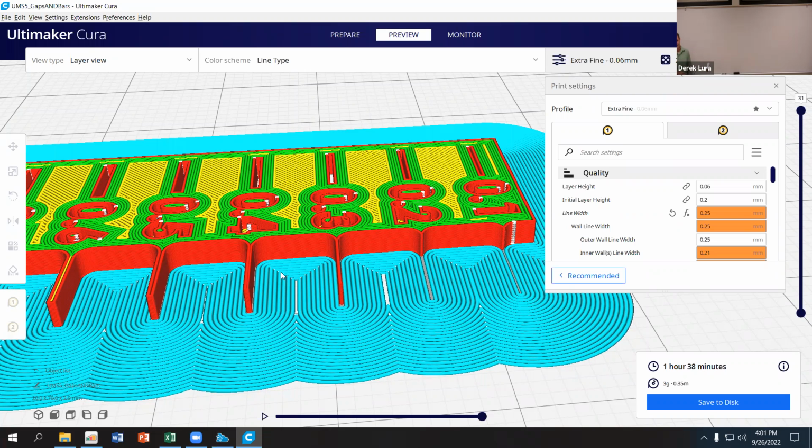So really you shouldn't change the width of the lines without also changing the nozzle diameter inside the machine. And if you go really, really small, the machine's going to have a really hard time pushing plastic through. And so your print speed is going to have to be really slow, or you're going to break the machine, or not break the machine, at least ruin your roll of filament. You're going to have issues printing that out. The same is true for the opposite direction. There's a limit to how much plastic the machine can melt and push through itself. And so if I try and do really, really thick layers, you're going to have issues from that standpoint. So there are bounds as to how fast and how slow you can effectively print things.